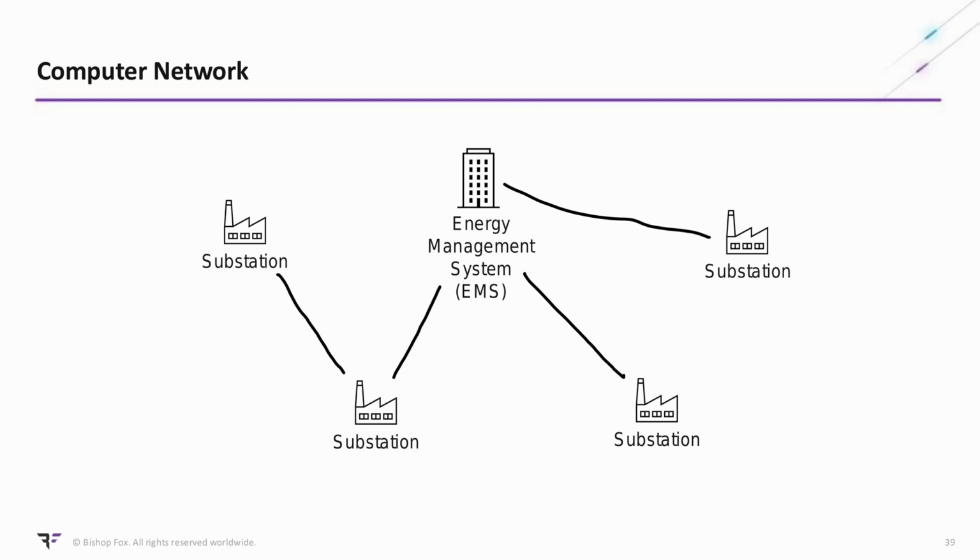So at the very top, there's an energy management system, or just EMS. The energy management system is a piece of software, as in it's like an implementation that sends computer network signals. But it's also a group of human beings sitting in a station somewhere that make decisions about how electricity should be routed and are remotely operating all these substations.